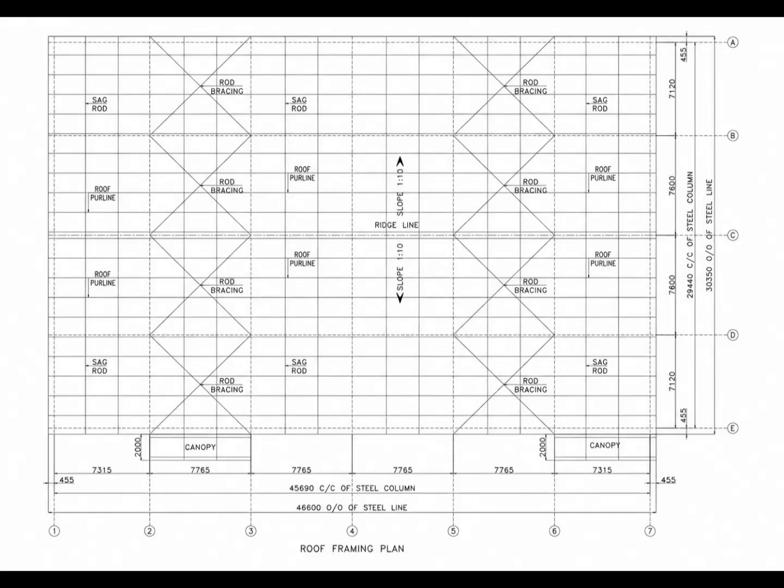For practical PEB detailing, this slide teaches us an important workflow. First, locate the member in the general arrangement drawing. Second, identify the surrounding structural members. Third, check its position relative to the building grids. Fourth, compare the information with another elevation or plan. And finally, verify the arrangement in the 3D model. This approach reduces the chance of misunderstanding a member when moving from drawings to modeling.